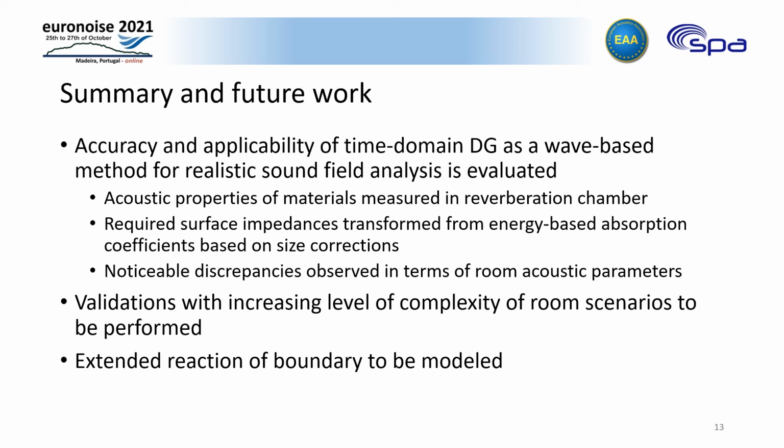To summarize, wave-based room acoustic simulations of a real open-plan office in the low frequency range have been performed with the time-domain discontinuous Galerkin method. The acoustic properties of materials are represented with energy-based absorption coefficients in octave bands, which are measured with the reverberation chamber method. From this input data, the required complex valued surface impedance data is retrieved by fitting the size-corrected Sabine absorption coefficients, assuming a monotonic absorption behavior within the interested frequency range.